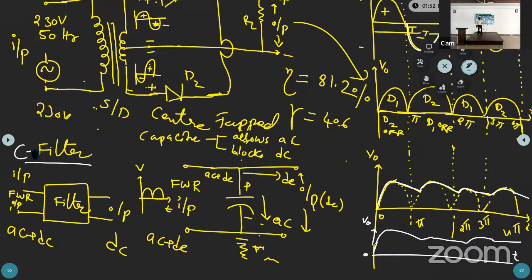Okay. How much voltage are we getting here? How much DC voltage? 0 to 9. The DC also 0 to 9 volts, right? It is not 0 to 9, simply 9 volts in the output. But our requirement for the electronic gadget is to produce an output of 5 volts DC. So we need to convert that 9 volts to 5 volts using regulators, that is voltage regulators. If it is over, then I will move the slide.